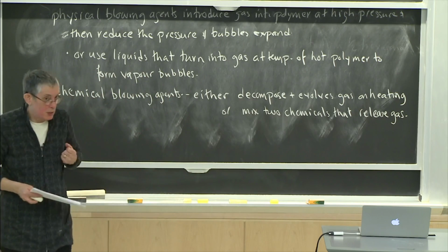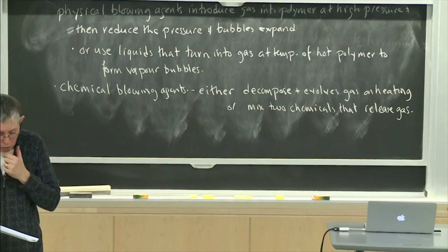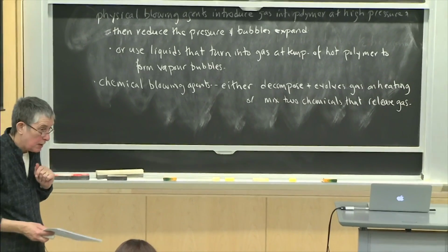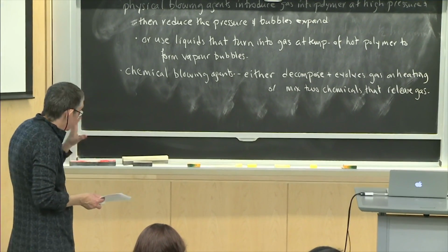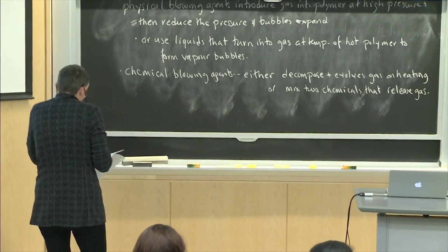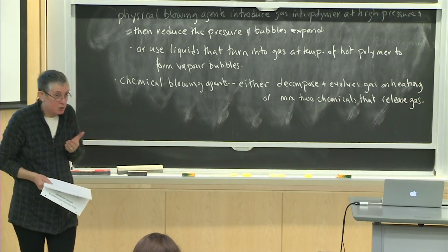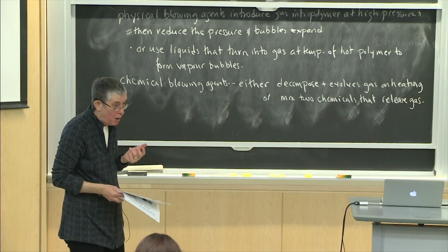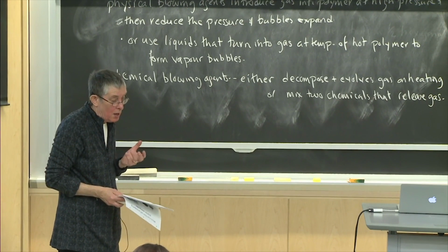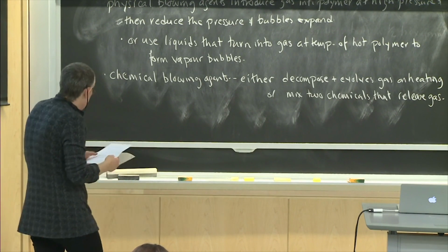So there's these different ways of blowing the foams, and there's many different types of these blowing agents, but these are kind of the general techniques. And whether or not the foam forms an open cell or a closed cell structure depends on the rheology of the polymer, so the viscosity of it, and also the surface tension.